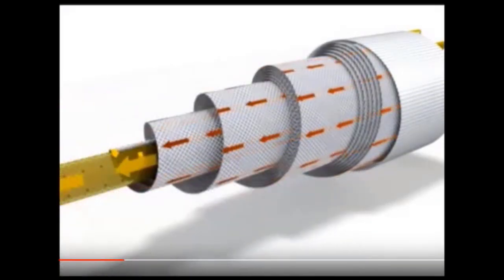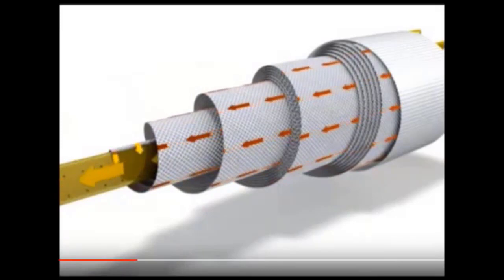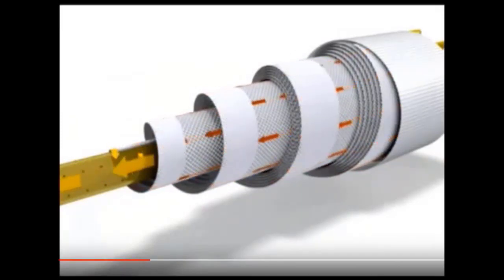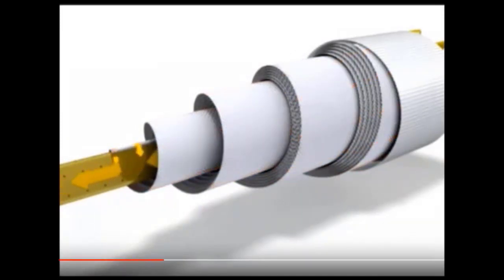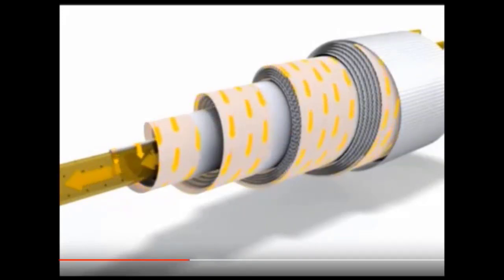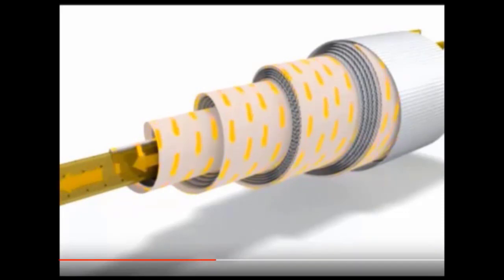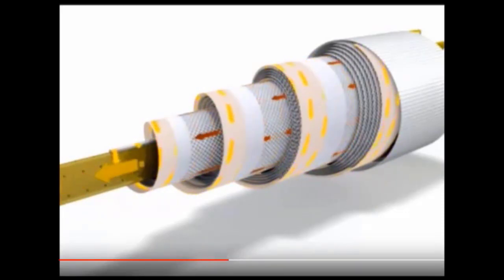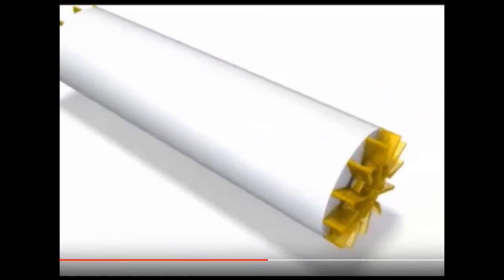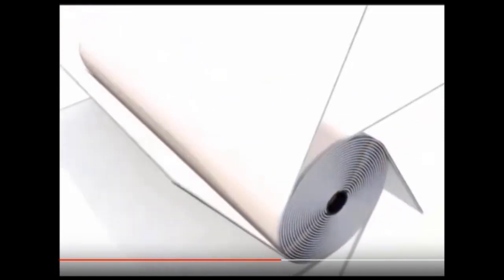This concentration effect is due to the fact that the transmembrane pressure, that is, the difference in pressure between the feed and the permeate side, induces a flow of permeate through the membrane layer. The membrane is constructed such that the permeate is transferred to a perforated central tube known as the permeate tube, from which it leaves. It may be easier to understand how this separation takes place by unrolling the spiral membrane, allowing a further look at the membrane construction.